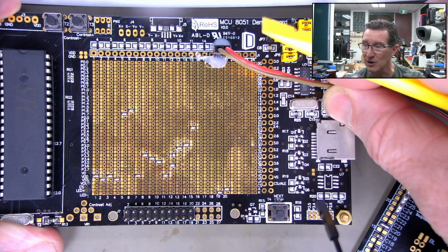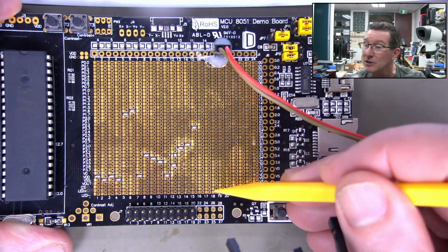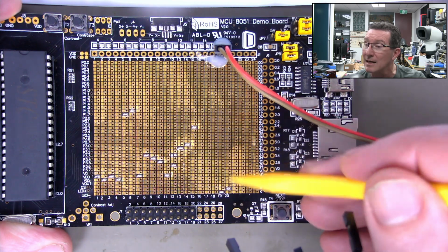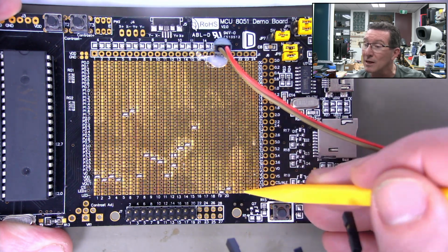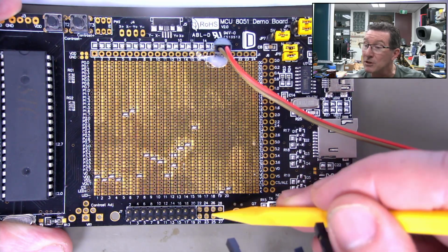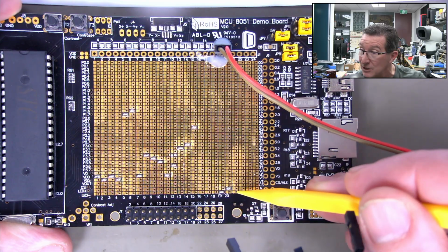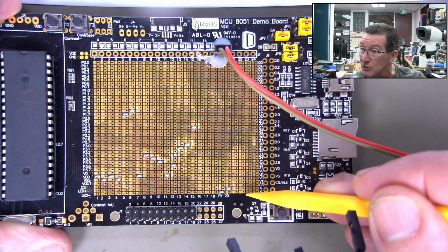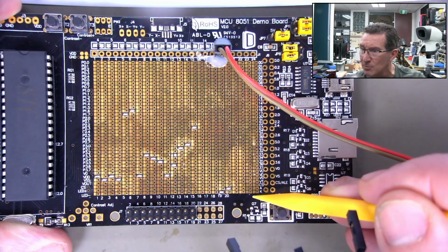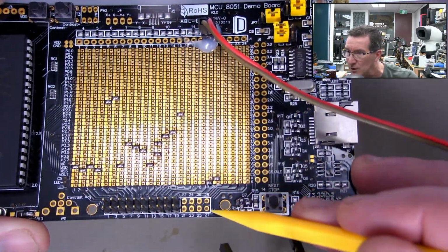But yeah, it looks like I'm going to have to reconfigure this. Although, hey, look, pin 16 isn't used, 17 isn't used, 18 isn't used, 19 and 20 are used, so I've got 3 spare pins there. If I put some extra pins in here, unfortunately it doesn't go all the way to 28, it only goes 21, 22, 23, 24. I'm not sure why they stopped the silk screen there. The traces seem to go to it.